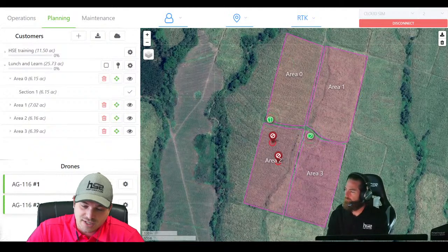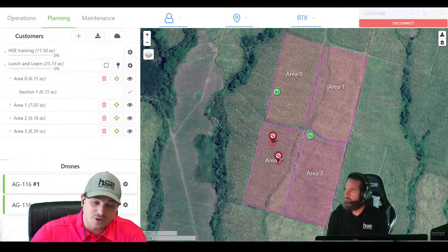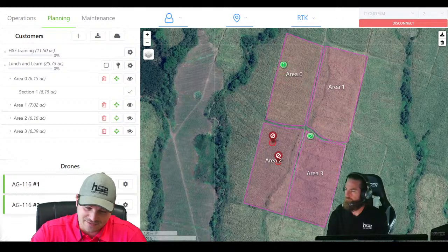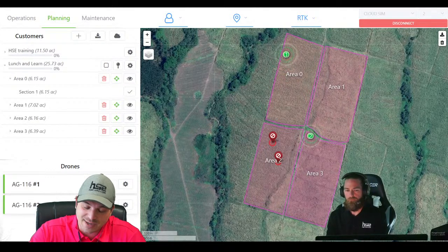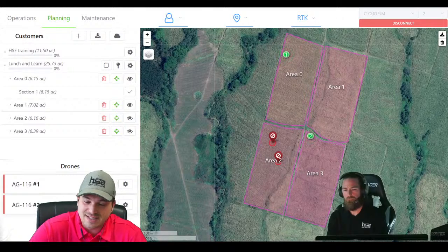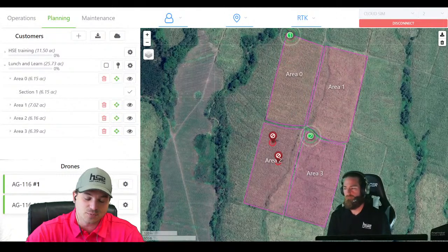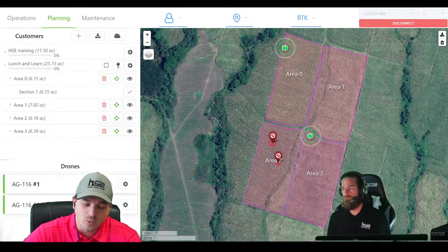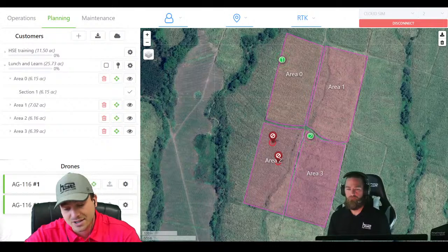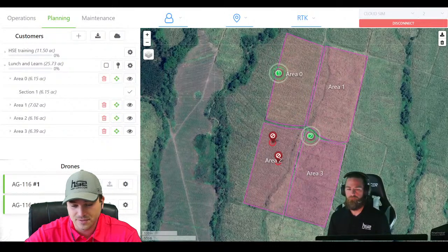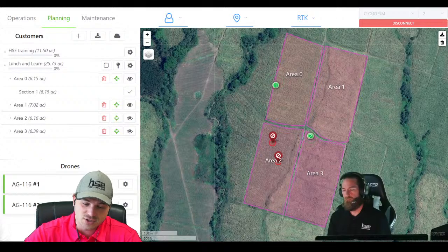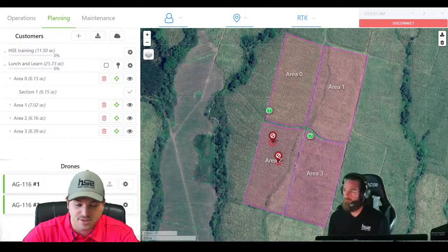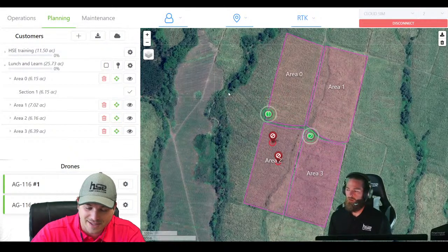Realistically, the technology that's available currently to be able to fly around obstacles effectively is very difficult. It's just not reliable to the point where we would feel comfortable implementing it into a drone the size of our spraying drones, which the largest models can be 130 pounds fully loaded. So it's always critical to plan for your obstacles, and you have the additional safety feature of the obstacle detection, obstacle avoidance to protect you in case you mismark an obstacle or forget to mark an obstacle. I hope that answers that question a little bit better.